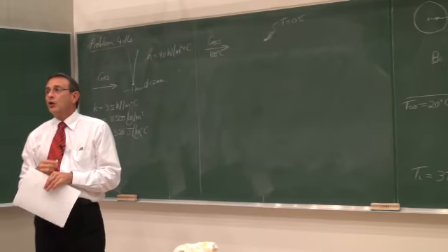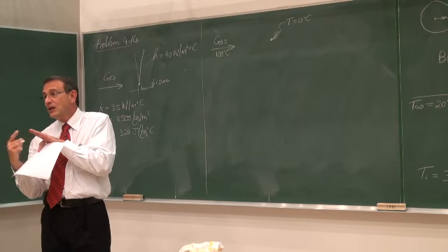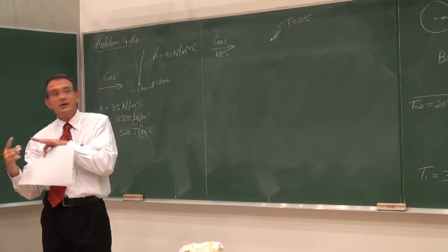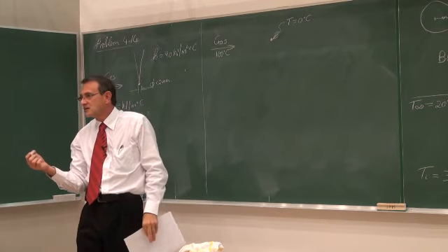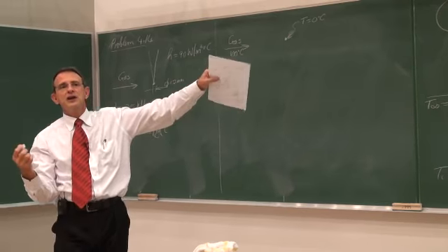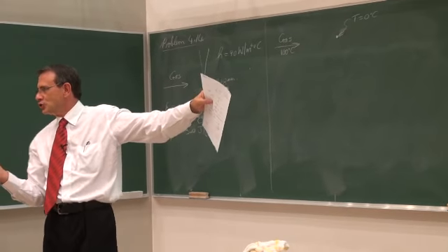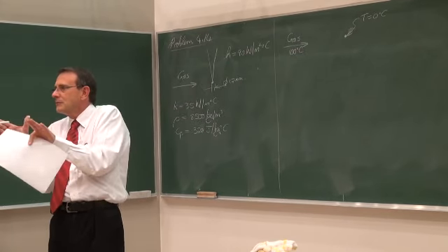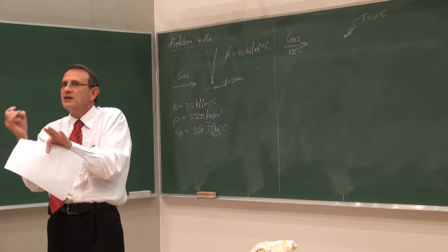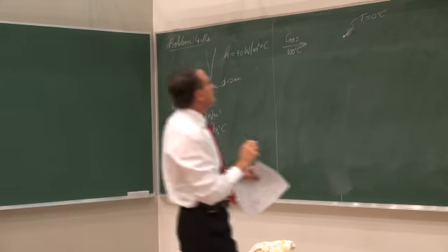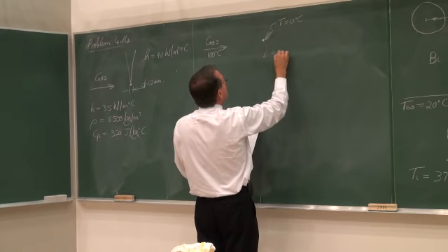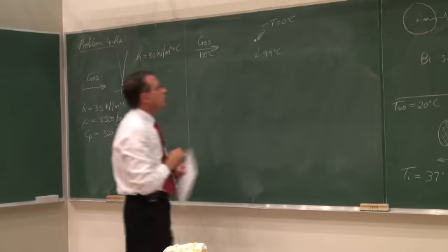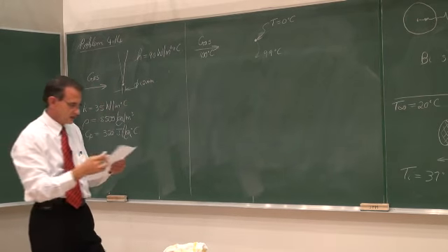What you're interested in knowing is how long will it take before this thermocouple measures 100 degrees Celsius. And if you are within 99%, then it's already good. So 99% means that we are 1% from the real measurement. So it's about how long it will take for this thermocouple to measure 99 degrees Celsius.